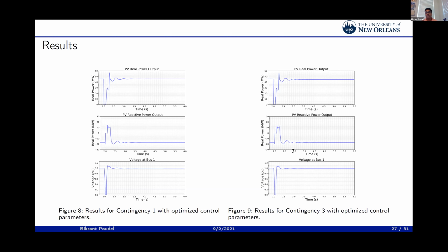We are selecting multiple contingency points, multiple weaker points on the system, and based on those weaker points, we'll do the optimization so that we are sure that the values we choose can work for all the contingency scenarios. And not only can you use just one plant, you can also optimize multiple plants. In the case of PSO, we have done up to 3 plants. So it can be expanded to any limit. And if PSO is not enough for a particular application, based on our problem domain, we can also use something like a genetic algorithm.